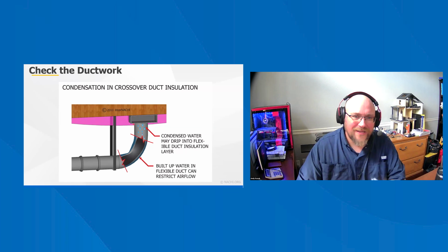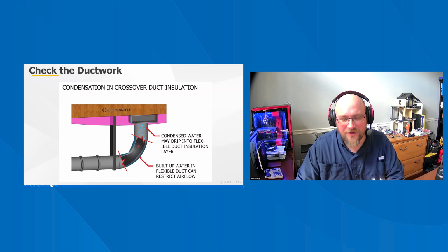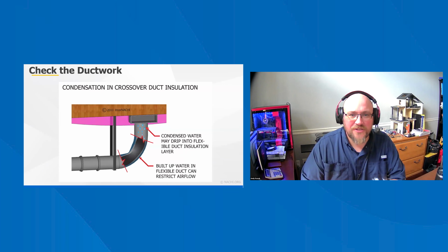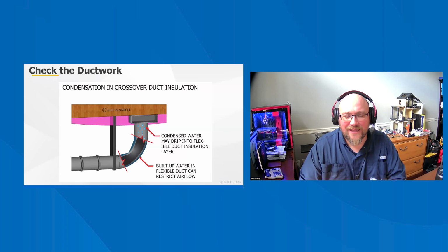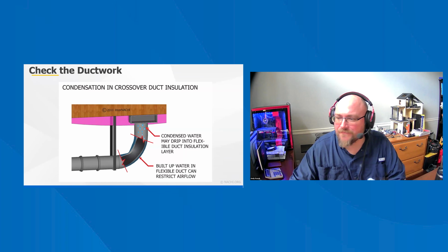But that just shows you how important the insulation is, because you have this super cold air in the summertime going through the ductwork and getting to this uninsulated portion. The ductwork reached its dew point, the moisture in the air condensed, and then it soaked into the subfloor. So pay special attention to those floor penetrations in unconditioned spaces that are not insulated, and make sure that there's no damage there.